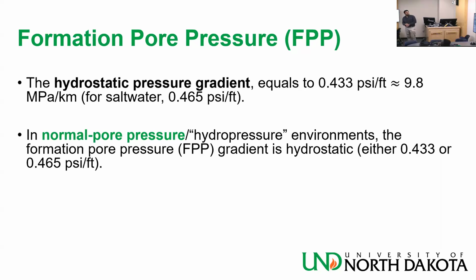It's a confusion because hydro comes from the ancient Greek word hydro, which means water. And that's the ancient word. The modern Greek word for water is nero. But in the scientific community, when you say hydraulic or something, it's something that has to do with fluid. We use it for fluid, like hydraulic modeling means fluid flow modeling. Okay, something about fluid flow. Doesn't mean fresh water. So if I ask you the hydrostatic pressure of this, it doesn't mean assume that this is fresh water necessarily. But if I tell you the hydrostatic pressure gradient is 0.433, it means fresh water. It's used interchangeably, it's very confusing.